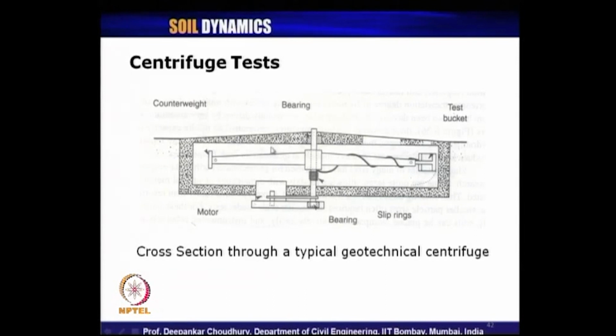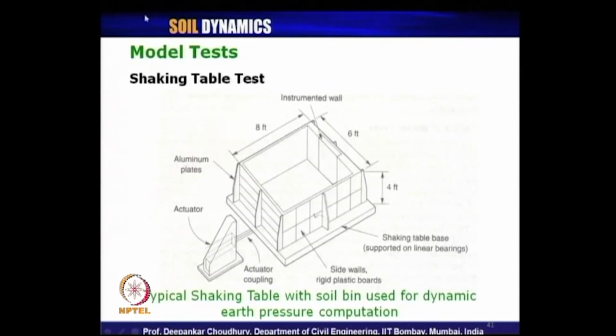About this point, this keeps on rotating and the centrifugal force is getting generated, and that is how the principle is used to scale up the model dimension which we use in our geotechnical engineering to a prototype or actual field dimensions. So, those of you who are aware of the centrifuge testing facility know the drawbacks of 1 gravity, 1G, model tests for our geotechnical engineering problems.